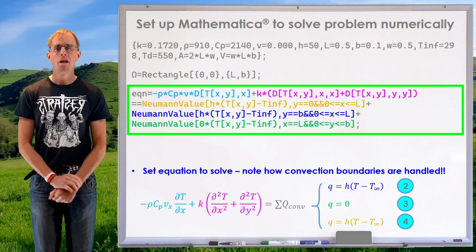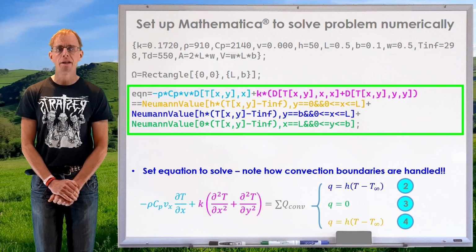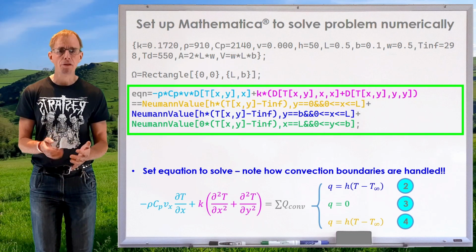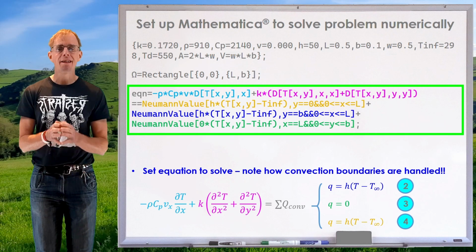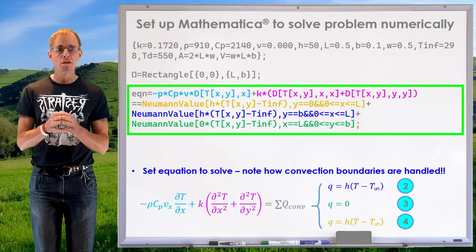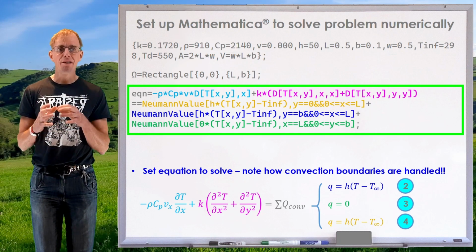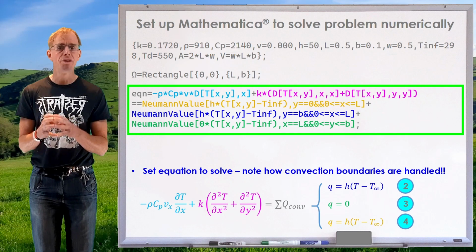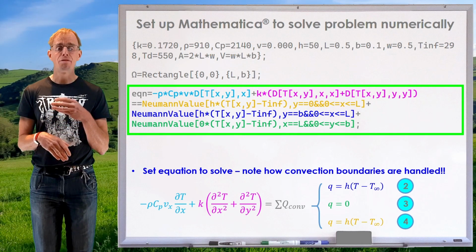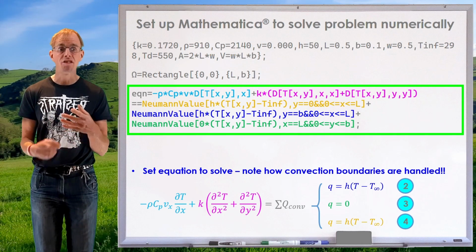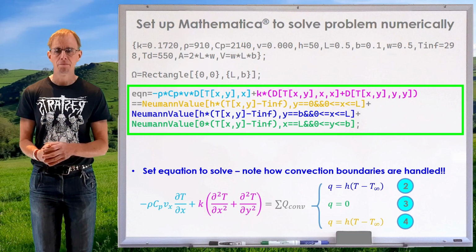The pink terms are the conduction terms. And again, we can see that K, the thermal conductivity, features. And let's again look at our differential operators. It's very similar to what we just looked at, except now we have 2 x's following the field that we're taking the derivative of. And that just means we're taking the differential in x and then in x again, so it's the second differential with respect to x, d2T by dx squared, written in partial form.